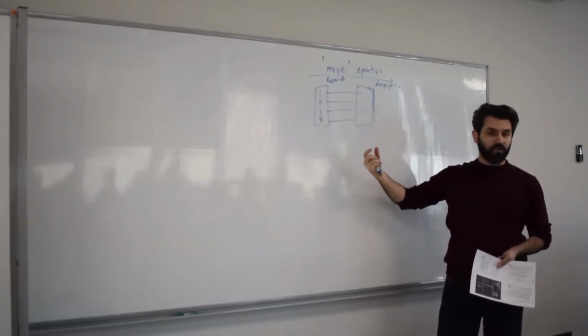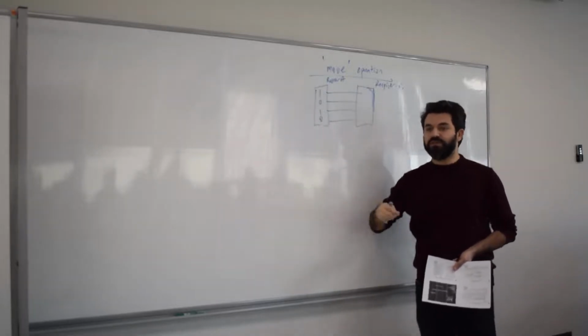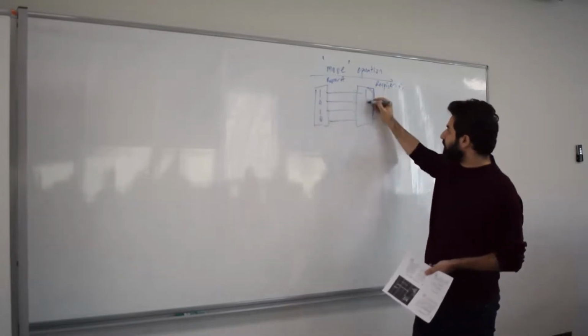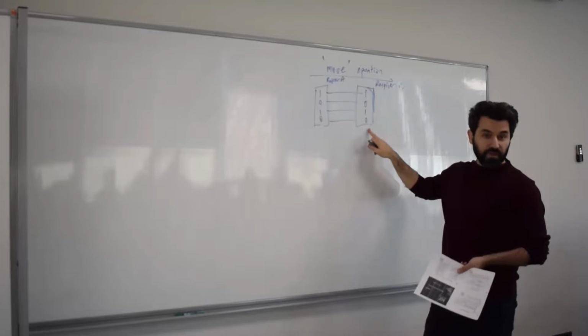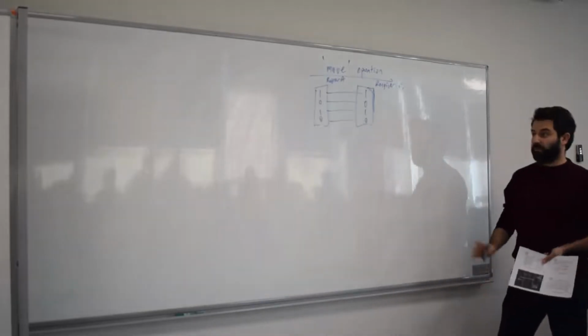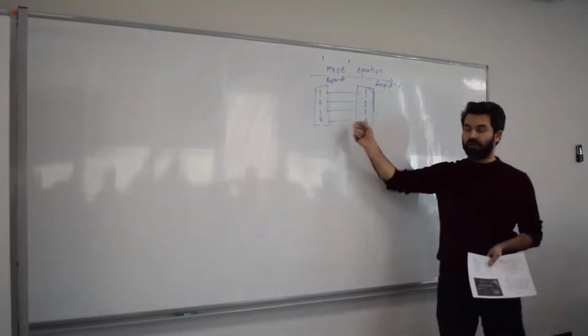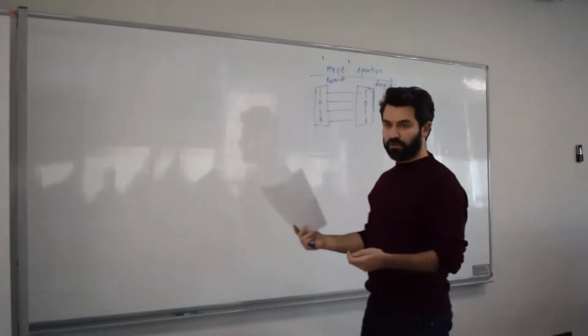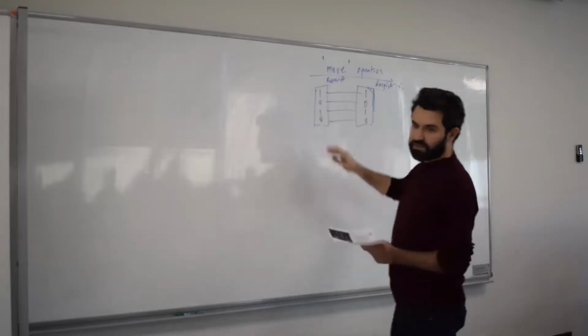In other words, a copy operation. Single clock cycle means that in the next rising edge, this 1010 value will be stored in register B. It takes only one clock cycle to copy that information using parallel wires. This is called parallel load or parallel transfer. So let me show you what's inside.